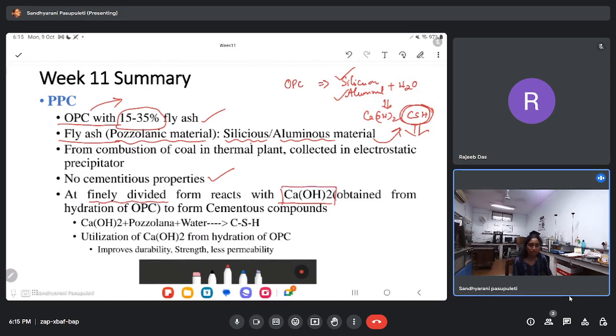One basic thing we all have to remember is how the PPC, the pozzolanic cement, sulfate attack cements or Portland cements, all other cements, are different from the ordinary Portland cement. The ordinary Portland cement byproduct is calcium hydroxide sometimes and also carbon dioxide. So we know that having a higher amount of calcium hydroxide will lead to sulfate attacks and durability will be reduced. So we have to reduce the amount of calcium hydroxide after cement hydration, and also we have to reduce the carbon dioxide emission.